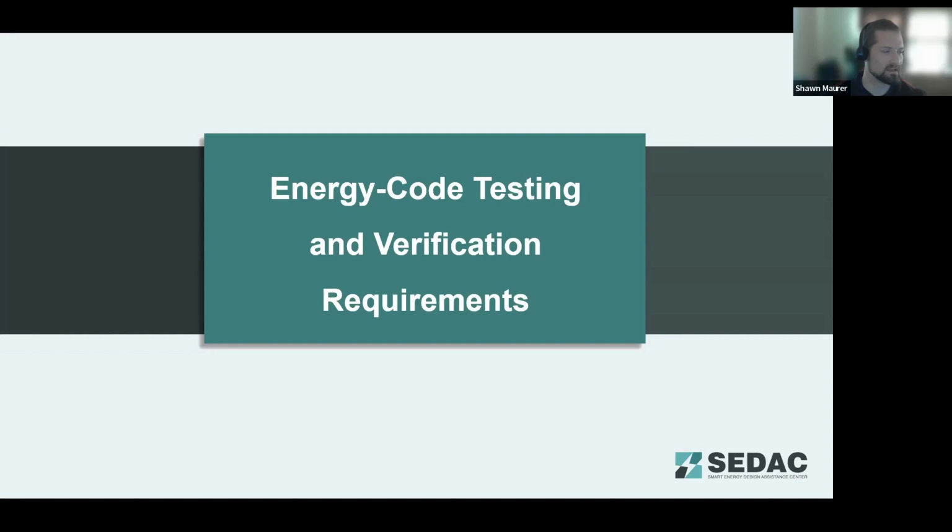And then what is true of duct leakage, the second response there, only high pressure ducts for commercial require testing. For residential, testing of the entire system is required if it exits the thermal envelope. It is mandatory for residential. You have to test it. The results of the testing can be traded off for the performance path. We'll touch on that later. But the testing does have to be done. It's required for residential. So that's incorrect for the first option.